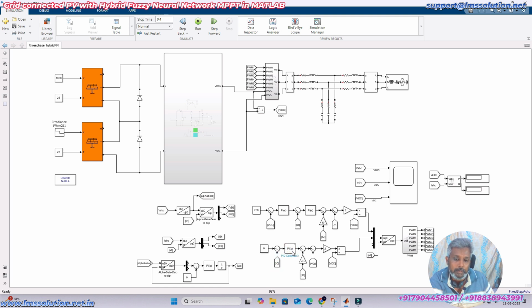and it is going to be processed by a PI controller, and then the PI control will generate the control signal. Here we are applying the feed forward decoupling control logic, and finally we are getting the control signal in the form of the Q axis. After that we are converting that control signal into ABC form by using the inverse Park transformation.